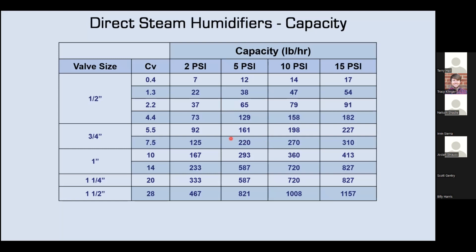However, with our controller, what we do is we modulate the opening of the supply or the control valve, and we dial back the span of the valve and make sure that we're not opening it to 100%, if your load is somewhere lower than the total capacity of the valve.